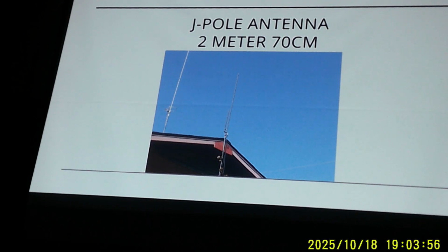Basically, that is a multi-band dipole antenna. It's like that picture that had the thing in the center with the wire going down. It's just a shortened dipole antenna. They're using the feed line as part of the antenna, so you don't have to get it 30, 32 feet high, something like that. You can get a little lower to the ground.